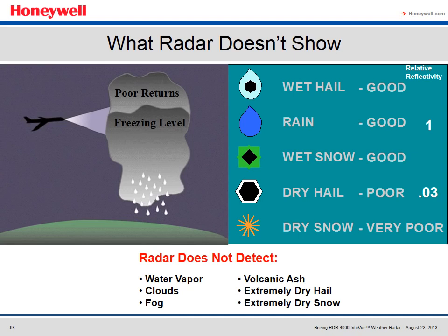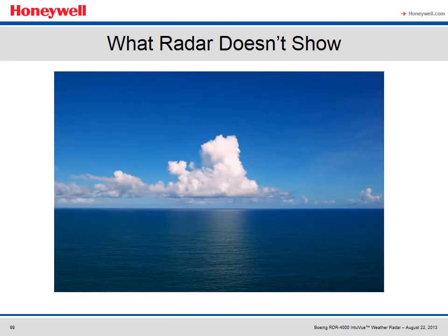At times, pilots may see a cloud mass and think that it should be shown on the radar display. Large white puffy clouds may be a developing storm cell, but they will not show on the radar until there is a sufficient size and quantity of water droplets available. Somewhat less obvious, immediately after a storm cell is dissipated and little to no rain is falling, a dark cloud mass may still exist that hasn't broken up yet due to the wind. The pilot can try increasing the gain to see if they are just below the green threshold, but there may not be enough reflectivity available.